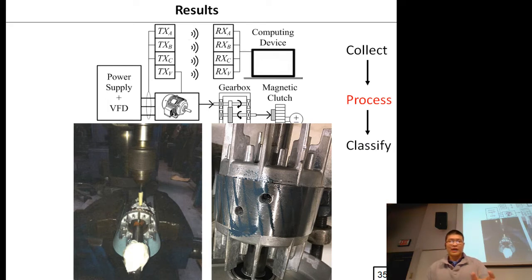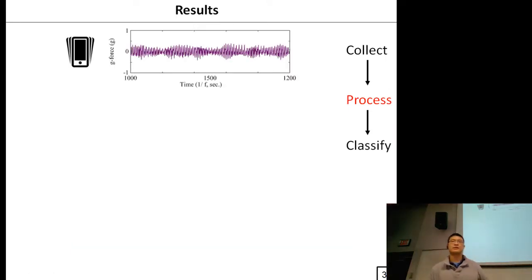And I test between a healthy motor and a faulted motor. So this is an example of a faulted motor where a hole is drilled into it to create rotor faults. This is drilled by Mahan Electric, the local Thunder Bay company, and compared with motors that don't have these holes drilled into them to simulate the defect. And so the results are as follows.